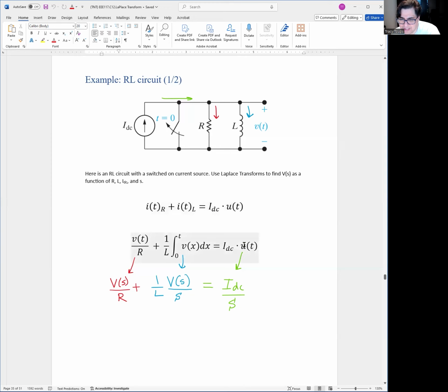Okay. Now, just looking at the second equation, it gets a lot messier because now you have an integral. And this is a first order differential equation, right? We can solve this, but it takes a couple of steps. Now, I could do my Laplace transform of this circuit. Notice these two things are added together, so I can swap them apart. So I can literally take V of t over R and swap it over to V capital S over R, because 1 over R is a constant, so that just goes with us. So this is an easy swap, easy Laplace transform.